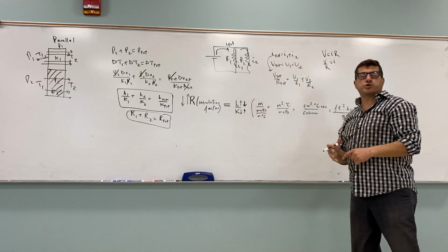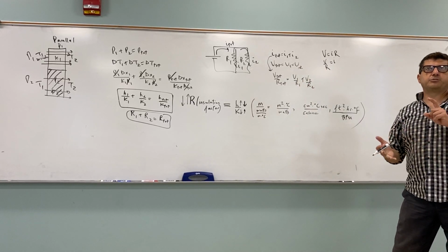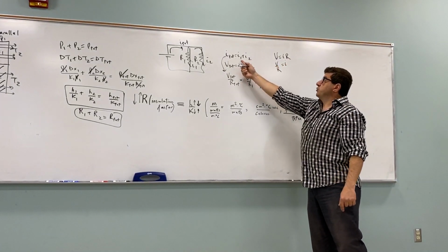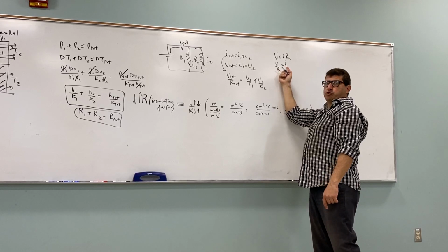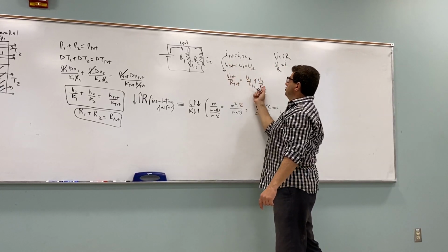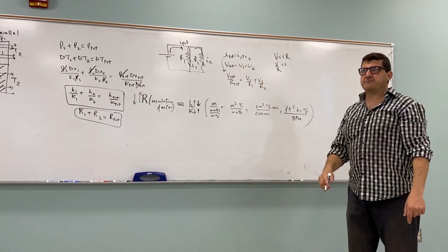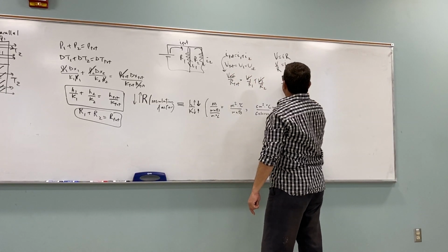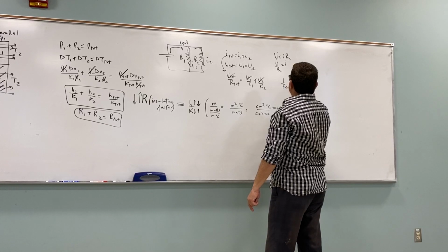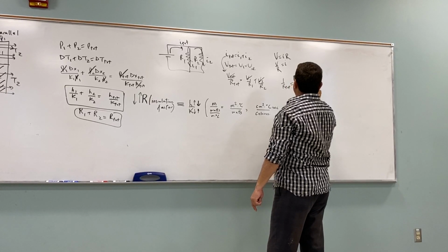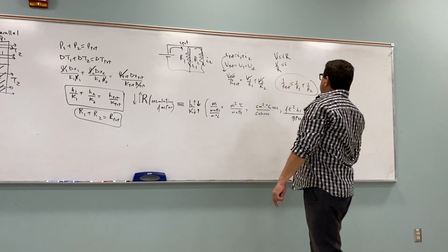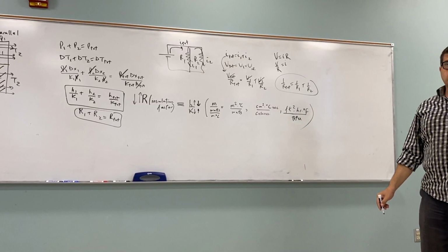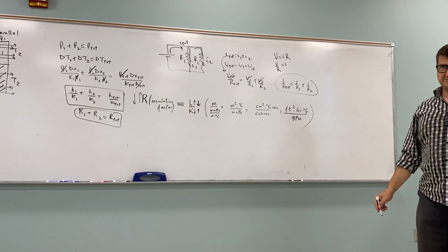So that's always what you're doing: what adds up, what is the same, then look at the equation, look at the one that adds up, solve for it, then substitute, and then get rid of whatever is the same. So then V1, V2, V total. So then 1 over R total is 1 over R1 plus 1 over R2. So electrical resistors, when you place them in parallel, they reduce each other, right?